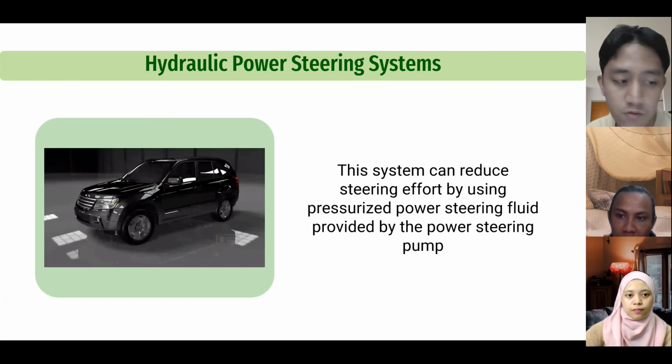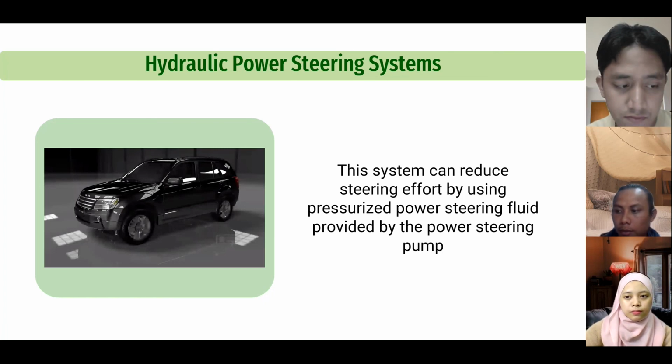When moving the front wheels, high pressure acting on the control valve acts to the driver. A receiver holds the power steering fluid. When the fluid returns from the steering gear at a significantly lower pressure, the receiver fluid level is maintained.